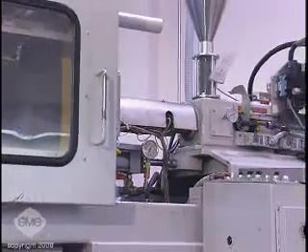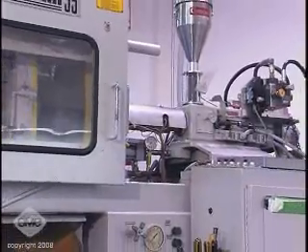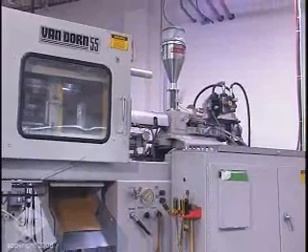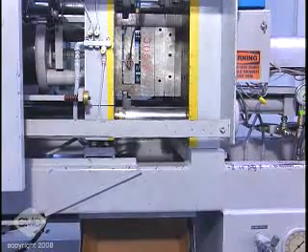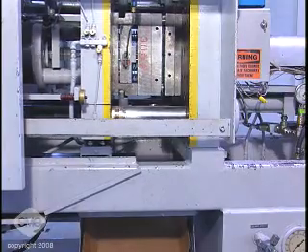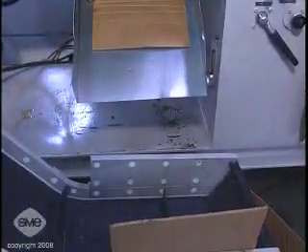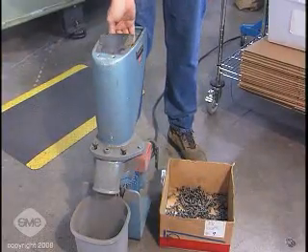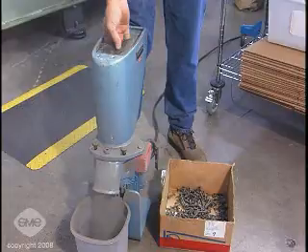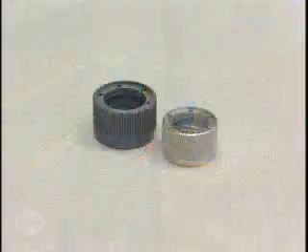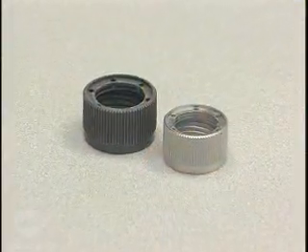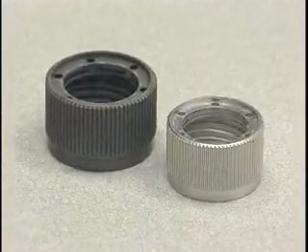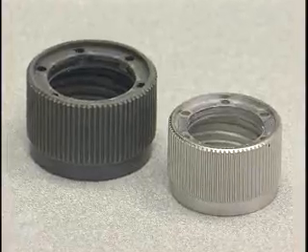Once it reaches temperature, the feedstock is injected into a mold, which may have one or multiple cavities of the part to be produced. Being in the green state as molded, the part is allowed to harden before ejection from the mold. Virtually none of the feedstock is wasted because sprues, runners, and even rejects can be recycled for reuse. As molded, the part is an oversized replica of the desired part. Thus, shrinkage in subsequent processing must be accurately predicted.